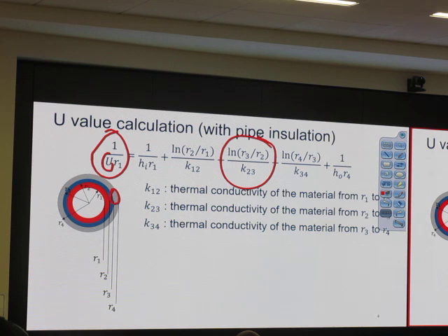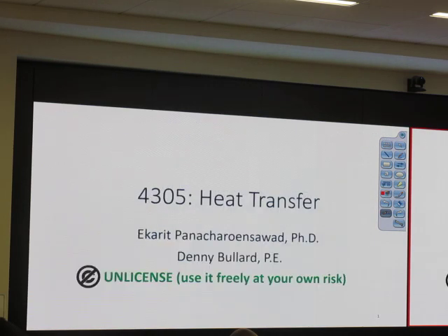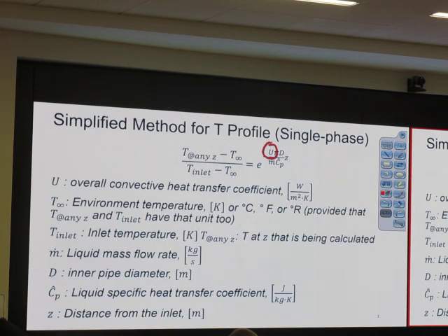Make sense? It is the maximum possible U value because when we add other heat transfer restrictions, the U value will go down, down, down. If I neglect all other terms and keep just that term, the U value that I get will be the maximum possible U value.